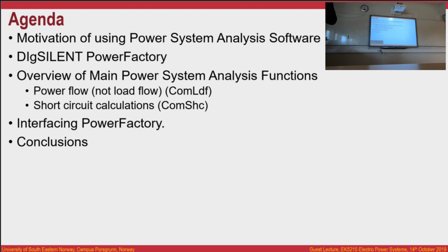I mean, PowerFactory is a very powerful software, but at the end we are using the software for more, very complex things. And one of them is that we are using the software as a proper calculator using another software. Have you heard about software in the loop? Software in the loop is when you have two software talking to each other. And the idea is that you can send orders to one, run some simulations, and then collect data and send back. That is something that is extremely useful.